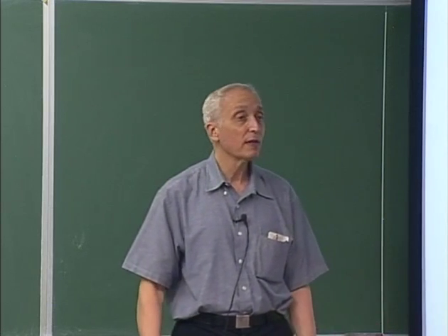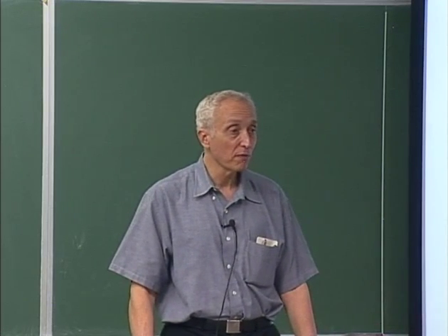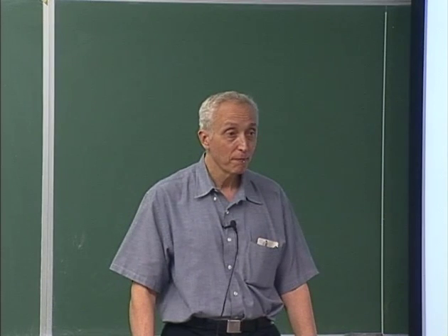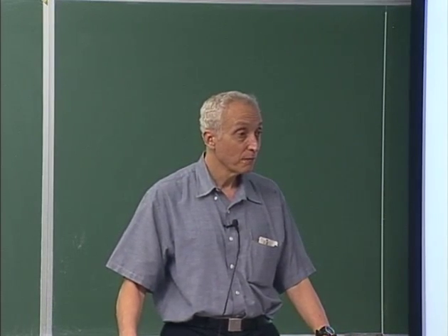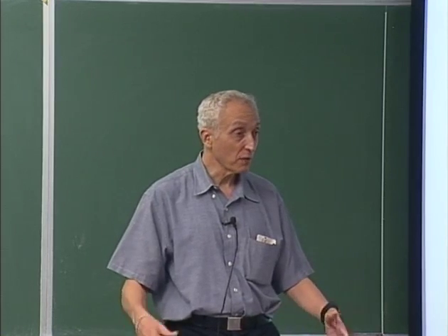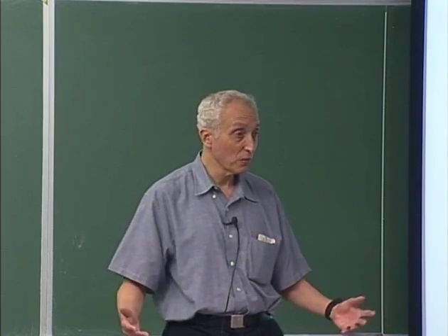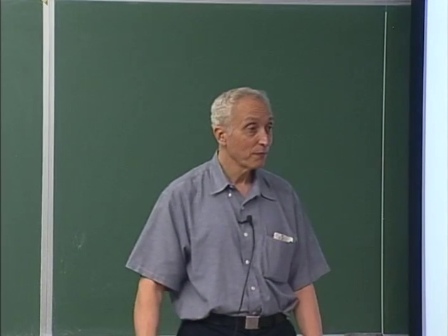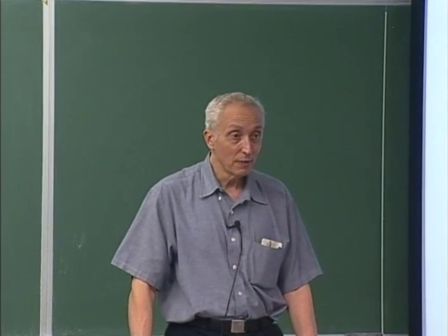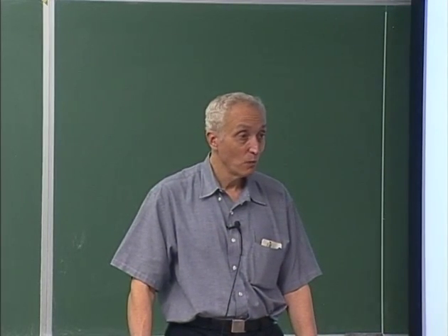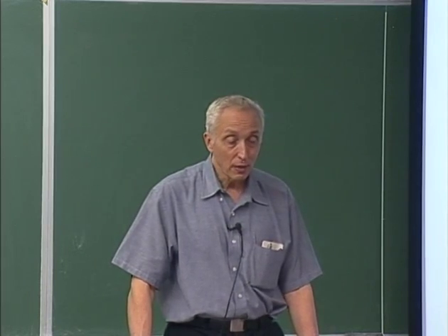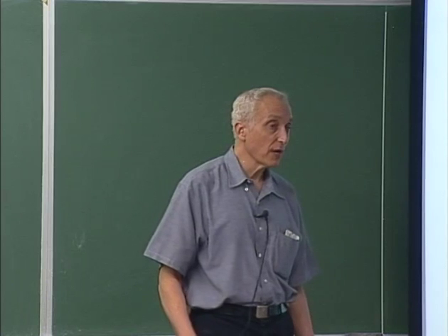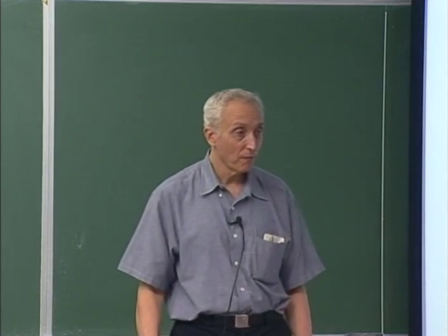What do we use in structural analysis to solve the finite element equations? What solution method? Just a set of linear equations, only that it's large. Yeah, you use a variant of Gaussian elimination.